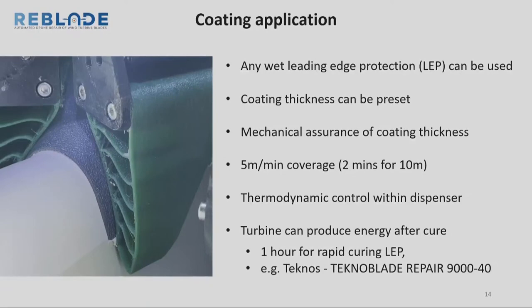If you use a very rapid curing LEP, and there's a research one that we've been working with by Technos that cures in an hour, it takes 2 minutes to do 10 meters of leading edge. You can do all 3 blades. The turbine can be up and running within a couple of hours in reality, which means you could do many turbines a day.